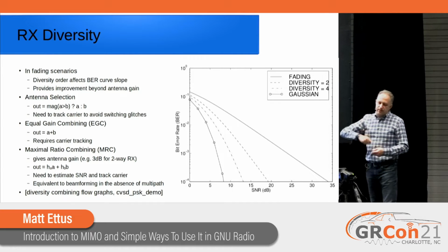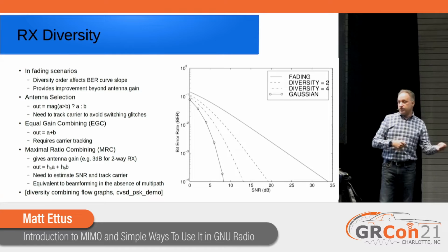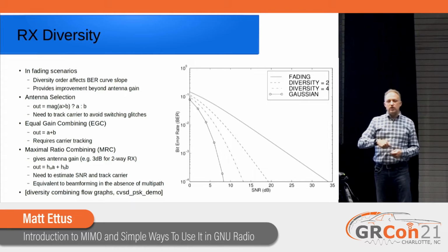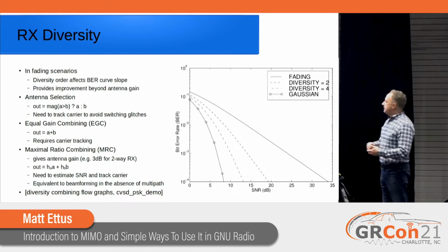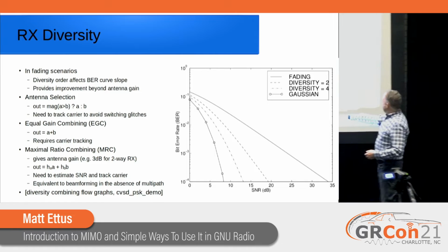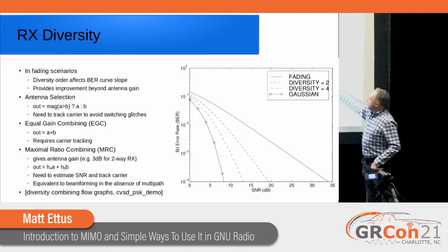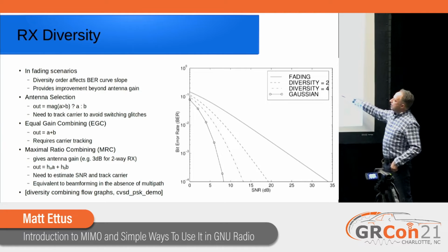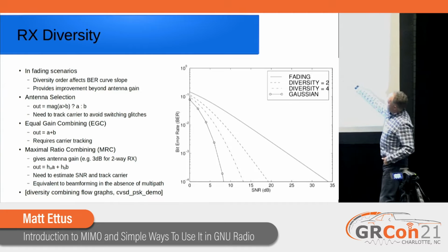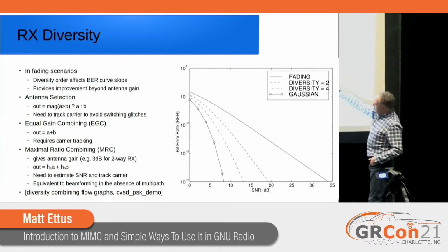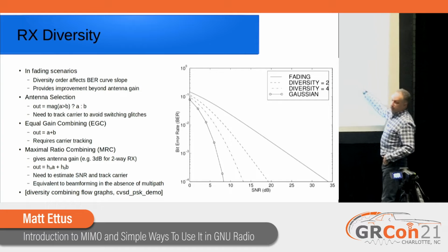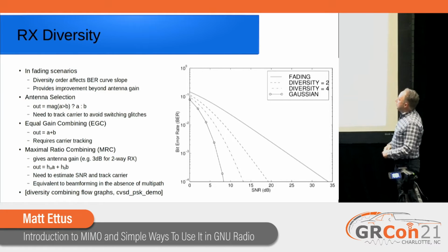It's almost like you have something effectively binary, either the channel's there or it's not. And so you get these deep fades, and thus you have to add lots of SNR in order to really get the low bit error rates, right? And this is the primary problem of fading channels. Rather than this sort of logarithmic or exponential drop-off, it becomes a very linear drop-off.